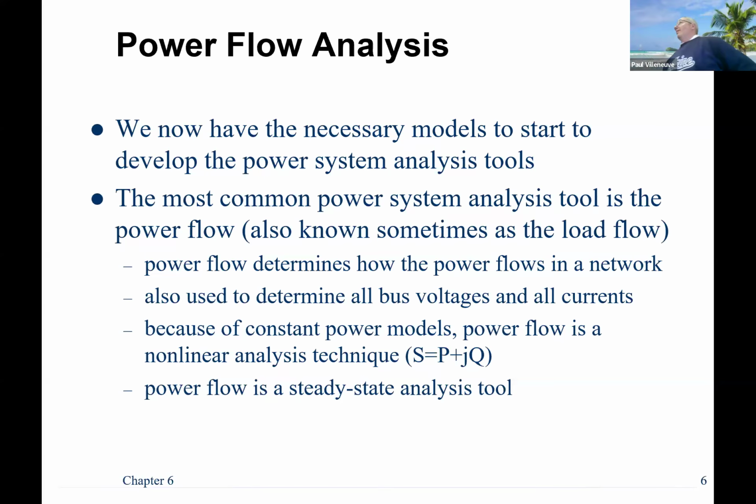Anybody here taking a semiconductor course? Op amps or BJTs or transistors or anything? What do you assume when you're using your op amps or transistors or BJTs? You have small signal operation, right? So you linearize about a very small point. So you pick a point and you assume small signal operation. You're not going to deviate very much from that point. And as a result, you can analyze with linear systems.